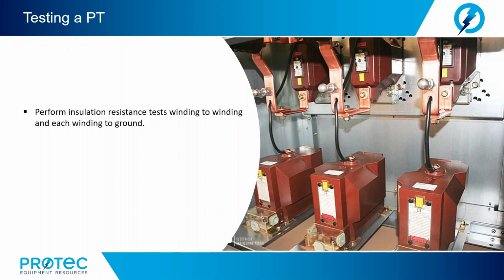Now, testing of a PT. First, perform insulation resistance tests, winding to winding and each winding to ground. Also, you want to test polarity and to perform a turns ratio test.